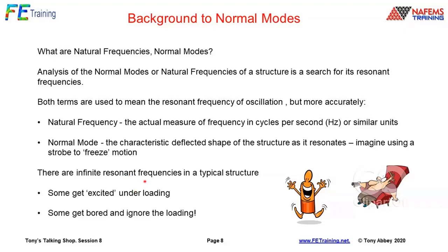Now, they're all there. They're an inherent part of the structure. They're sitting there, and some get excited under loading. Others never get excited and just ignore the loading. So, for example, in that gantry I saw, because I'm hitting it laterally, all the vertical modes just are not interested in that response.